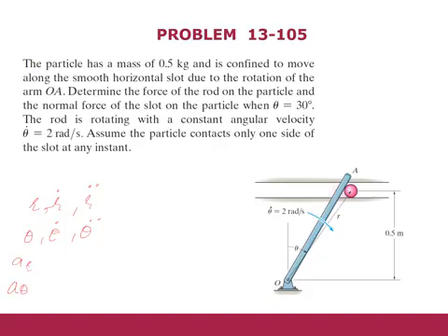So we know the governing equation and we apply Newton's second law of motion, which is the summation of all forces equals mass times the acceleration. If the forces are in the radial direction, then it will create acceleration in the radial direction. Similarly, if we have forces in the transverse direction, then we will have acceleration in the transverse direction. So in this component of the acceleration, we will put the values of these variables and find the forces in that particular direction. This is the procedure which we will follow.